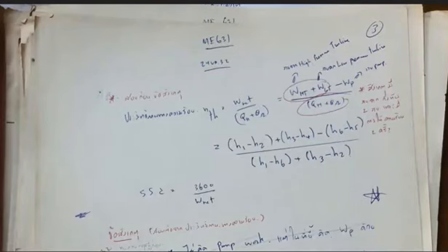Since now we have two stages of turbines and also two stages of heating, the formula for thermal efficiency will be something like this: work net divided by QH plus QR, where QR stands for reheating, equals the work that we get from the high pressure turbine plus the work that we get from the low pressure turbine, minus the work that we provided to the pump, divided by QH plus QR.